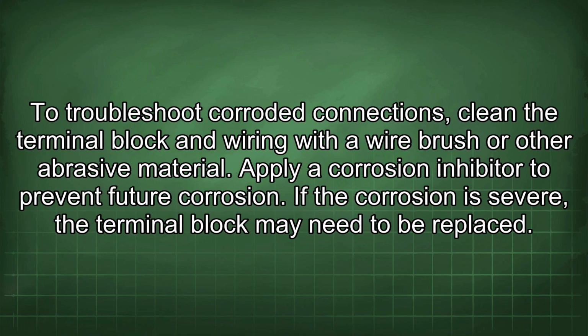To troubleshoot corroded connections, clean the terminal block and wiring with a wire brush or other abrasive material. Apply a corrosion inhibitor to prevent future corrosion. If the corrosion is severe, the terminal block may need to be replaced.